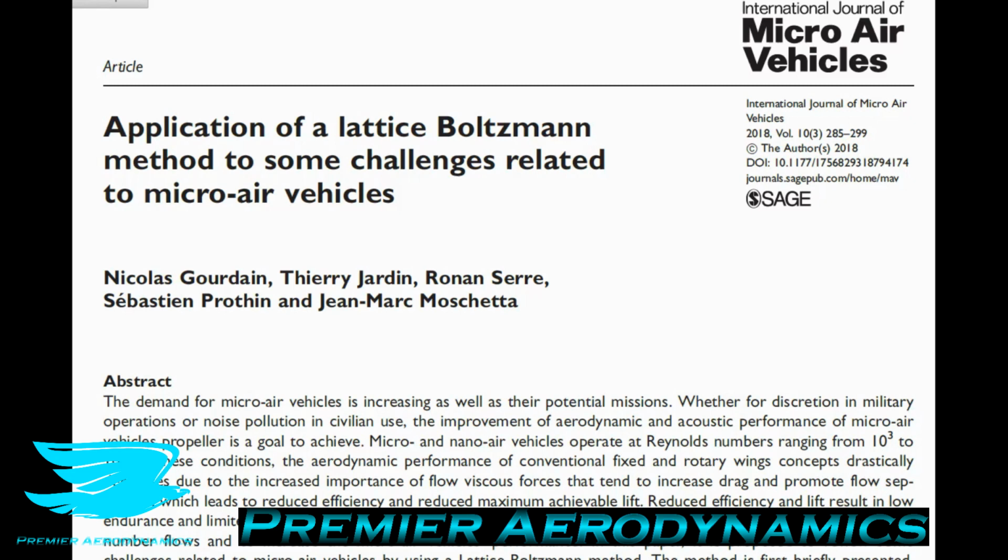So up until now, the Navier-Stokes equations use these equations, which are effectively four equations, with three for Navier-Stokes and then one with continuity. And what they do is they look at the flow from a sort of macroscopic point of view. So you get your flow and you divide it up into cells, and in each cell, you calculate the velocity, the density, and the pressure. And these are all macroscopic properties for this cell in general. And this is a very powerful tool, and CFD is done very nicely using Navier-Stokes equations.